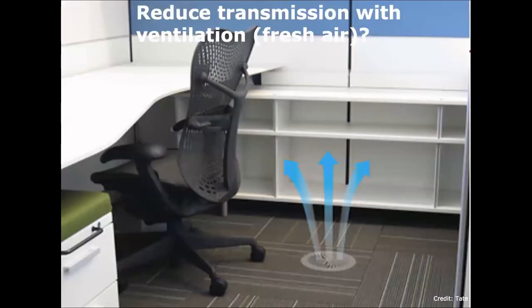The third method to reduce COVID transmission is ventilating the room. The role of ventilation is to introduce outdoor fresh air into the classroom and dilute COVID viruses. You can create ventilation simply by opening windows or doors if outdoor air is not polluted, such as by wildfires. Some classrooms have dedicated mechanical ventilation systems that use a fan to blow fresh air and deliver it into the room from either ceiling or floor level. In this exhibit, we'll focus on ventilation through the floor, also called underfloor air distribution system.